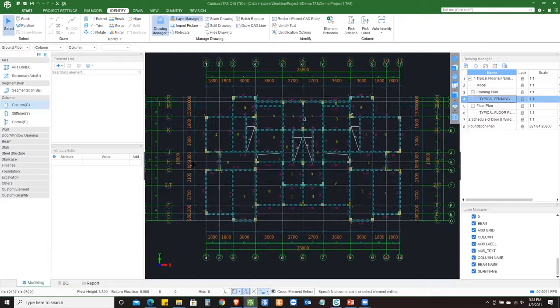All the shortcut keys are the same as AutoCAD. So that is a great point. You have L for line, TR for trim, EX for extend, and all of that. It's all similar. It's because the software has research and development integration with Autodesk, so they make sure that everything is working together. All right. So that is that.